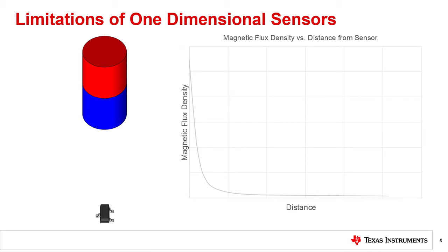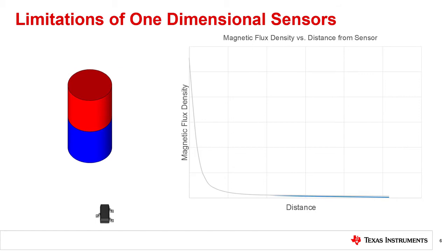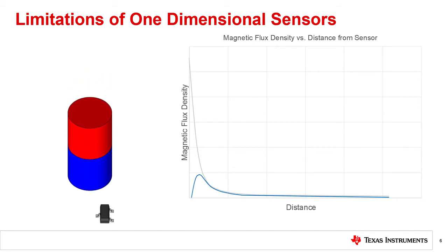Let's suppose that our magnet cannot be aligned properly. If we offset the sensor from the head-on approach so that it is no longer aligned to the pole of the magnet, we will observe at larger distances that the measured magnetic field is very similar to what was measured before. Also, the magnetic flux density appears to rise at about the same rate at first. Then, as the magnet continues to approach, the flux density begins to change direction, and the output drops to zero.